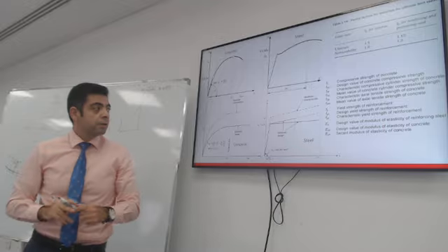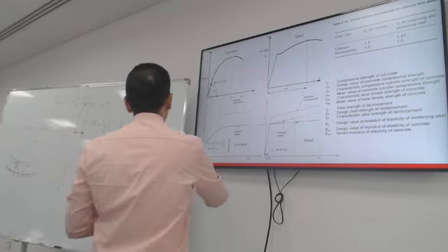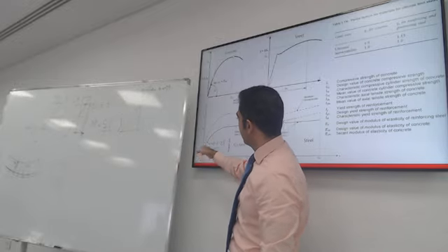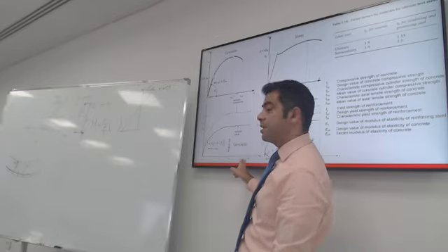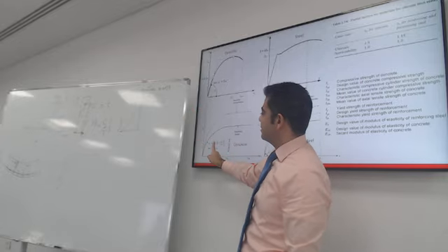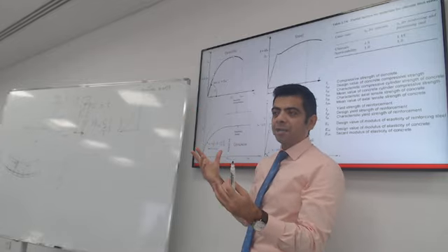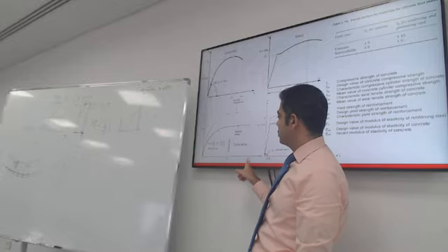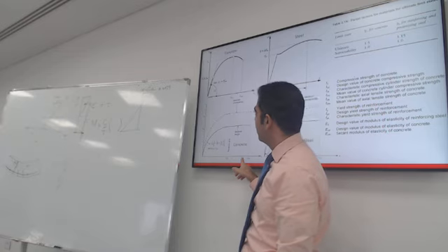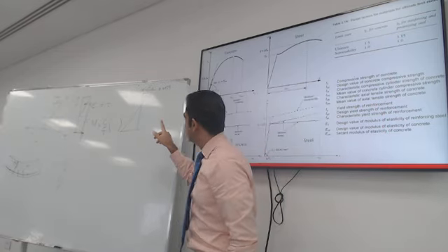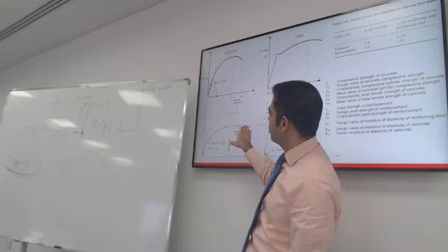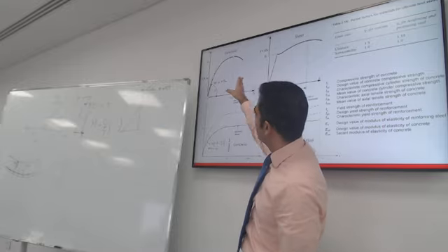All right, so where does that number come from? This number comes from the maximum strain. The bottom side is the strain, the top side is the stress. If this is the code idealized curve, the maximum strain is at this number over there. It's the strain epsilon cu2. It's the maximum strain that the concrete can handle, above which compression failure can happen.